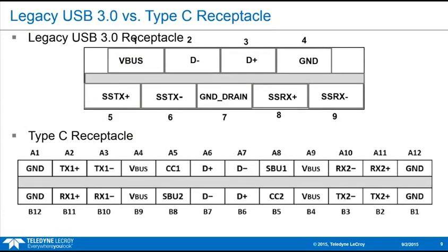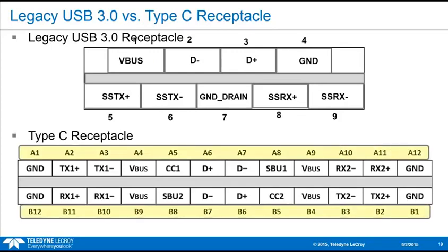Any discussion about power delivery really has to start with the pinout of the Type-C receptacle, because it's such a huge part of understanding how the technology works. To make the cable flippable on the new Type-C receptacle, they're basically creating a mirror image of the pins in sort of a top and bottom row alignment.